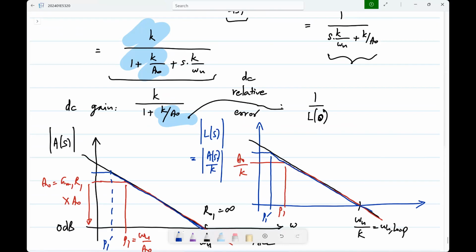Okay. So this is useful to understand all this, because as circuits get more complicated, you don't want to throw everything in the model. If you do that, you will get something very complicated, which is very hard to interpret. So now if you are asked to comment on the transient response of this, I think you can safely say that it is more or less the same as what you would have without that resistor. Only thing is, it's only the steady state value that is changed. Okay. This is fine. The circuits will get more and more complicated, and we should have ways of analyzing them.